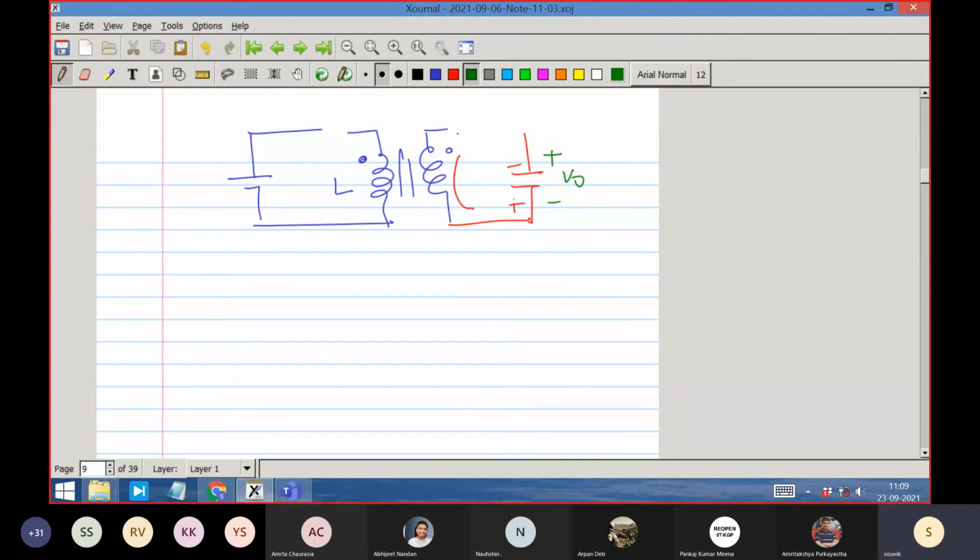So now this diode, if I look at it, this diode is what? Cathode to diode. So voltage polarity wise, this is now conducting. This current will force it to conduct. There is no red color. Let me do red color. This current will conduct. There is no way that it can avoid conduction. This way, this diode is now conducting. This current has to be continuous. It will force the diode to conduct.